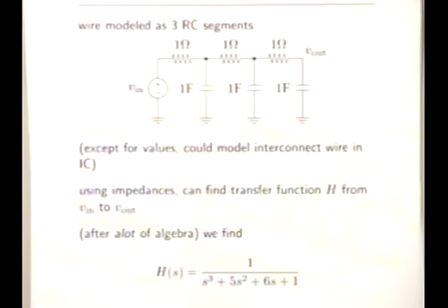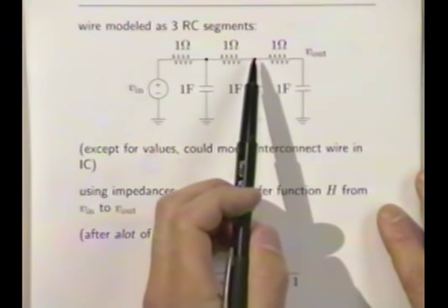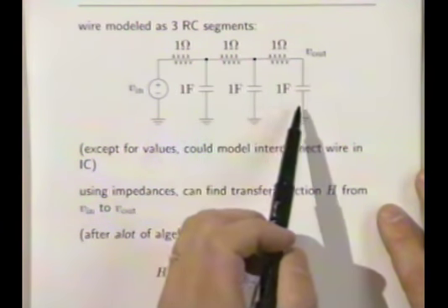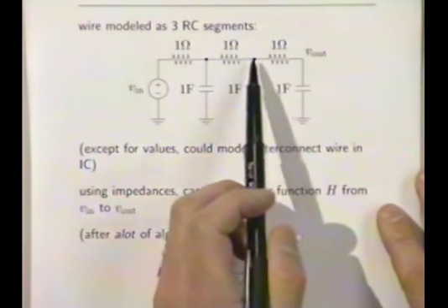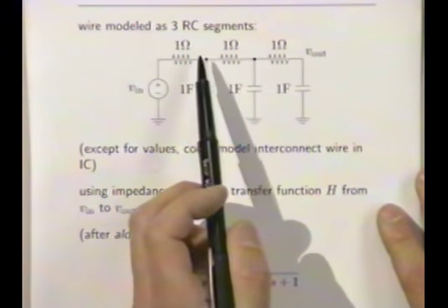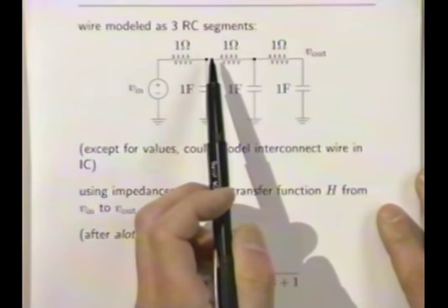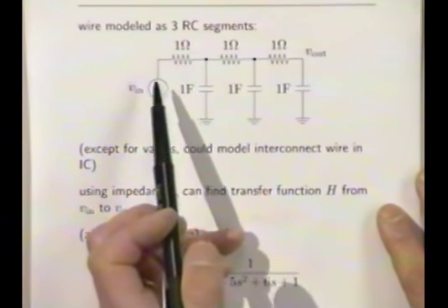Exactly, right. Physically, what happens here is this capacitor doesn't charge at all until it's charged by the voltage here. So this guy doesn't even start to charge until this voltage rises. This voltage doesn't rise until this capacitor charges. That doesn't happen. This only charges when the voltage here rises. Okay? Voltage here rises, well, that starts rising immediately, right?